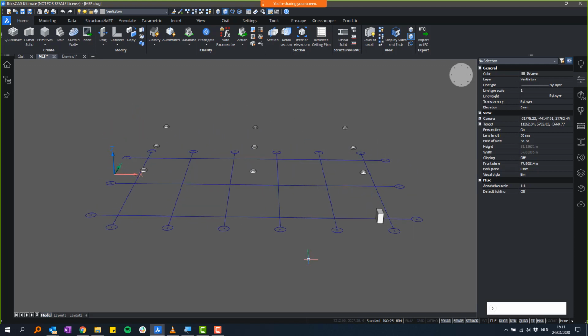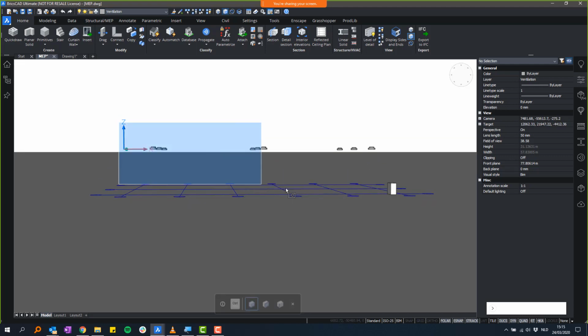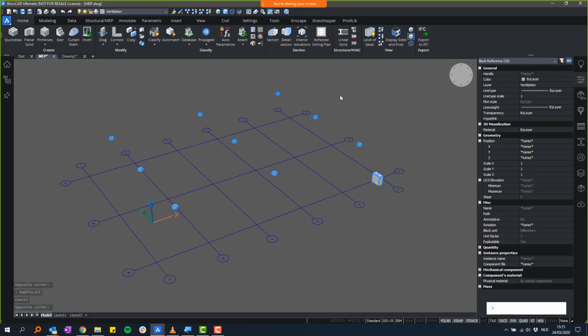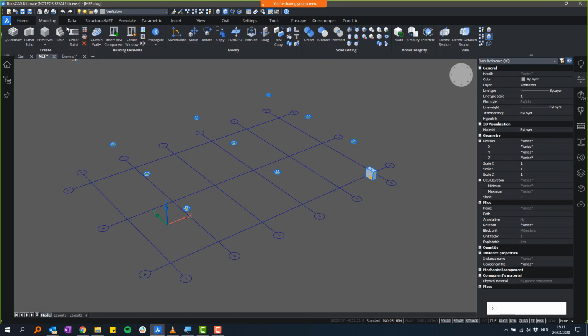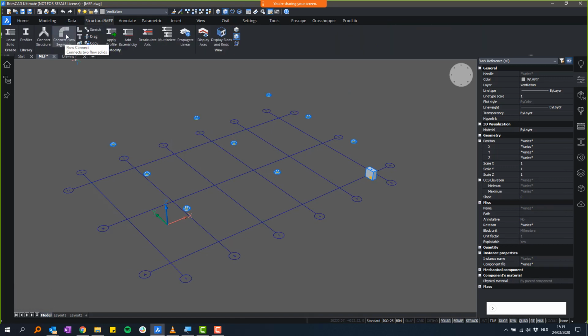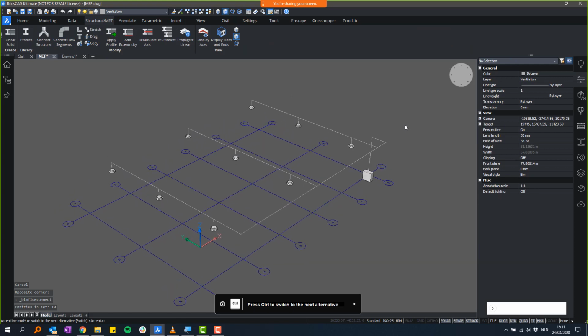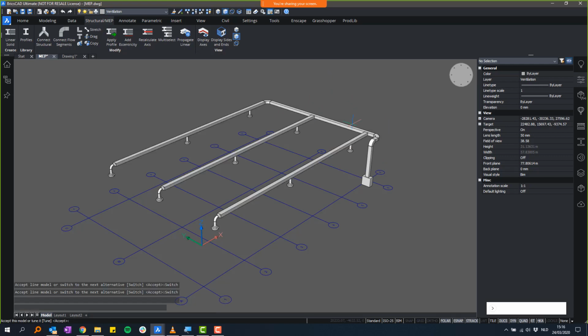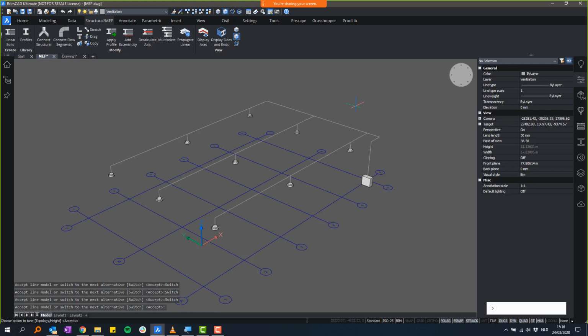So for example, we have this very simple layout of some flow terminals here, this main unit here, that we can connect using the flow connect tool. And automatically it creates already some sort of branching. Now this functionality is fairly new and it's still being developed, so it's still being improved. But what you see here is already available in the product. So you can choose between different layouts, fine-tune the layout a bit if you want.